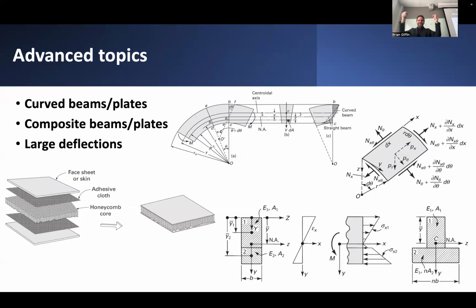But if it was initially curved and you're trying to pull it apart, what'll happen, as you might imagine, is it'll try to move more and more towards a straighter and straighter configuration. So as I continue to stretch it out, it goes from initially curved to eventually more straight. And to do that, it actually has to bend into this straight configuration. So in spite of the fact that I'm only trying to apply axial loads, at least along the secant center line, if you will, of this member, it effectively develops these bending deformations.